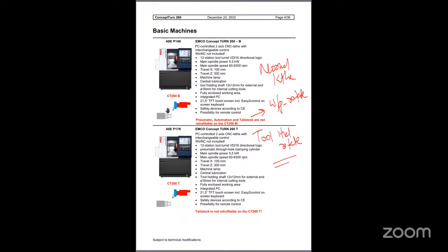Using this, we can do side drilling, face drilling, slot milling, small milling operations, tapping. The C axis will position the angular position of the workpiece, say 90 degree, 180 degree, 270 degree. We can drill different holes at 90 degree, 180 degree, 270 degree, etc.